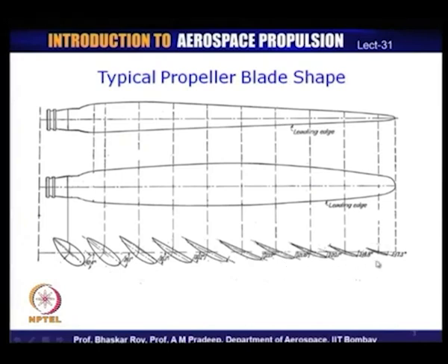These are not the same aerofoils made thinner, these are indeed different aerofoils altogether, because at the tip, if we go back to the velocity fields we were talking about, the resultant velocity V r incident on this leading edge is going to be rather high, and this is likely to be high subsonic for most of the modern aircraft propellers.